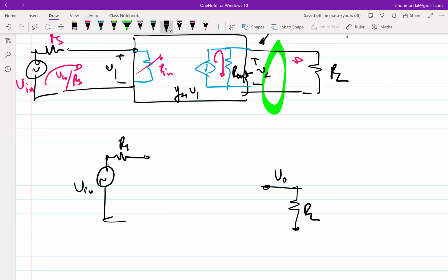So the argument that we were giving was, if we observe the difference between this input terminal, let's say I call it VI, and the output terminal, and we take some action in such a way that that difference goes to 0, then whatever block we will be manufacturing should behave like a voltage source, should behave like a voltage controlled voltage source.